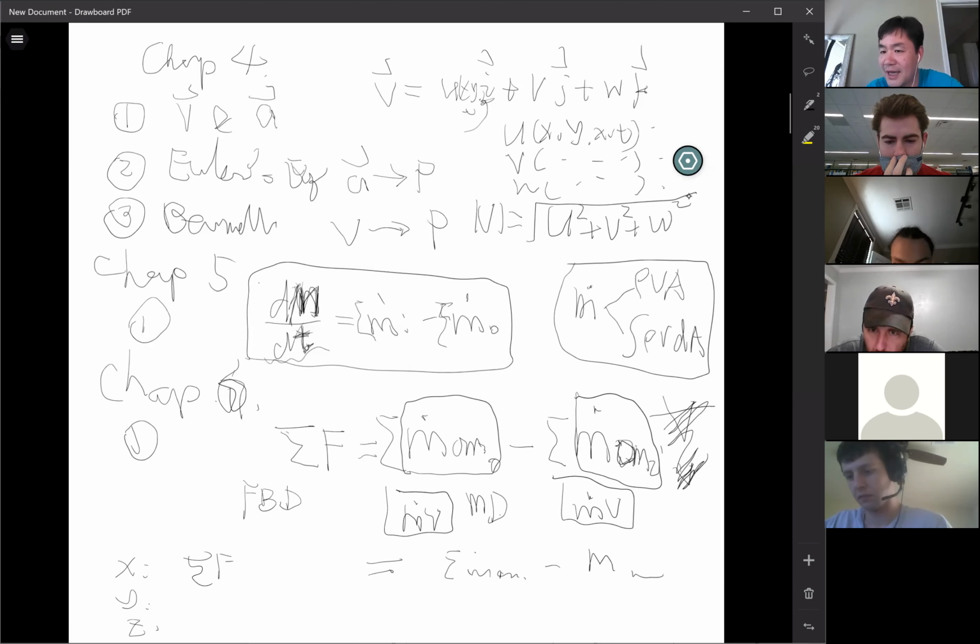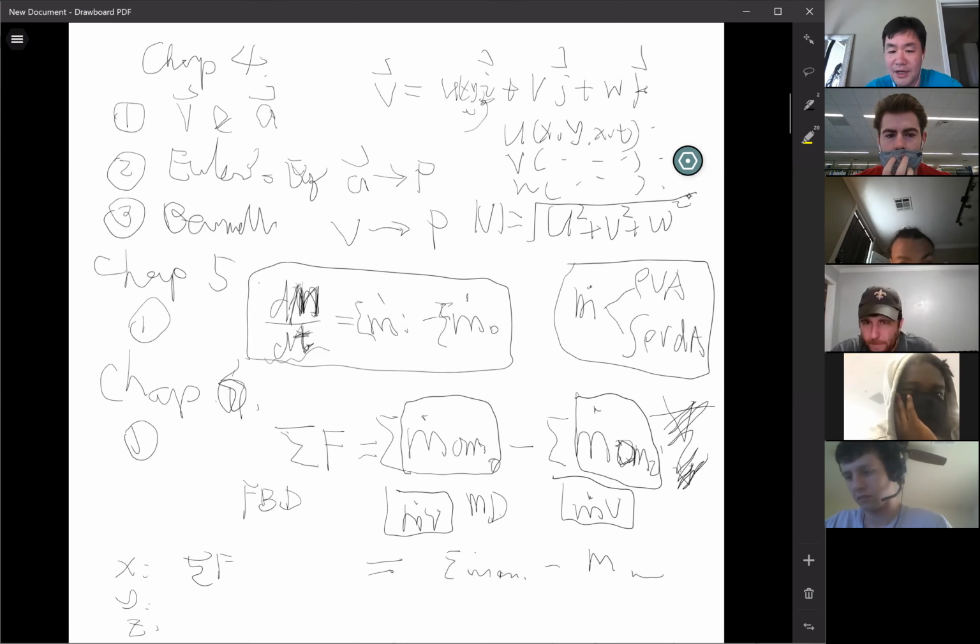Don't just look at the mass flow rate or velocity direction. Momentum as a whole has direction. When you draw the momentum diagram, you put an arrow, right? The arrow represents the momentum. Look at that arrow direction to decide whether each term is positive or negative.